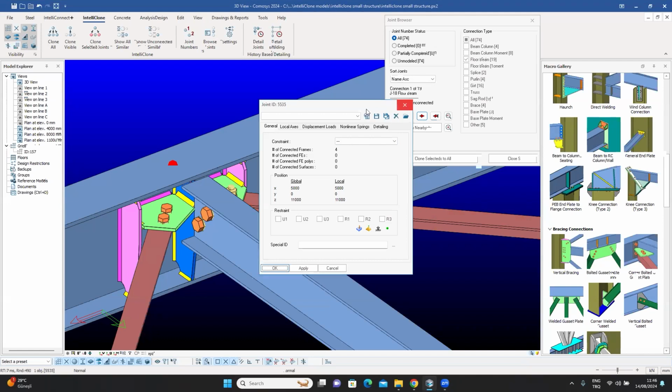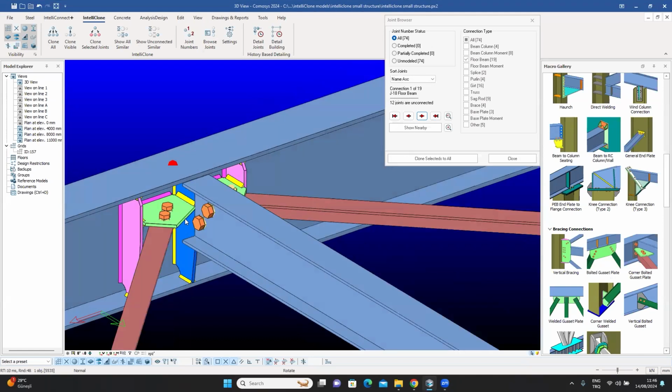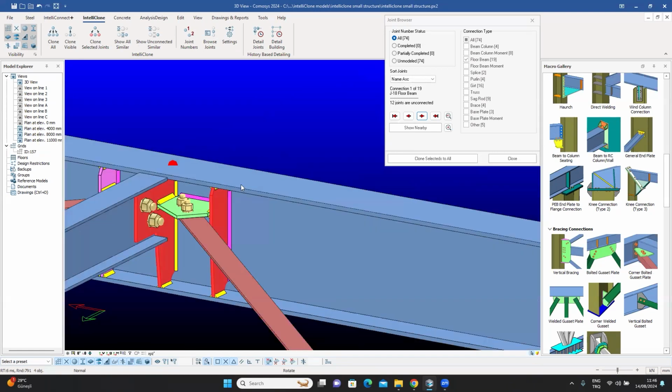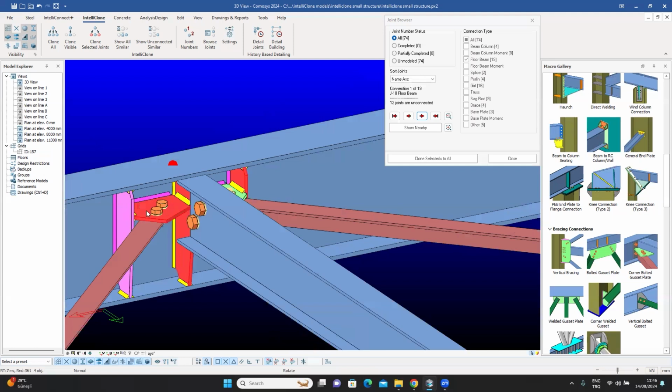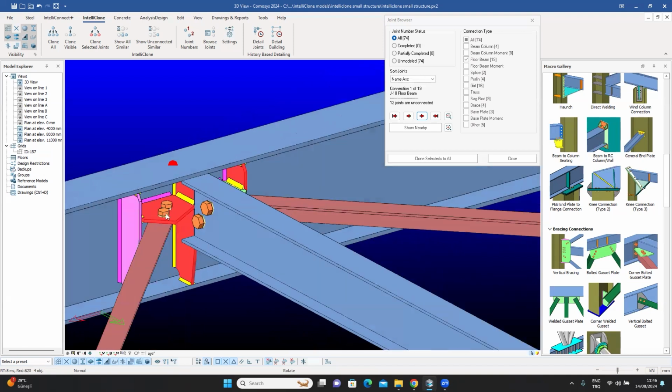And so the joint holds the key information to everything. I select this joint and I select any element from each macro. So I could select maybe this fin plate and the plate on the other side, so one element from each macro. I could select 2 or 3 elements as well. It wouldn't matter, but even one is enough. I don't need to select the macro symbol itself.